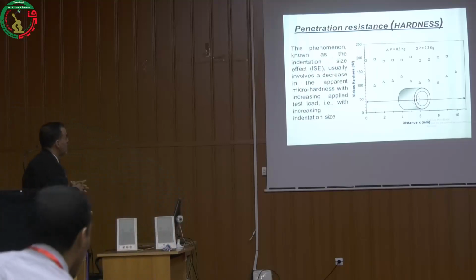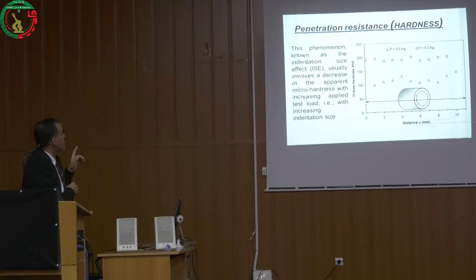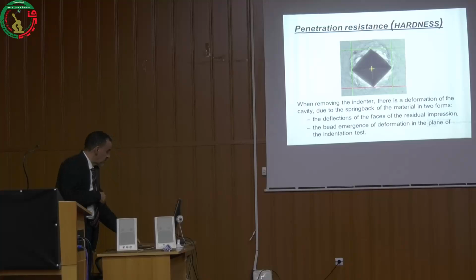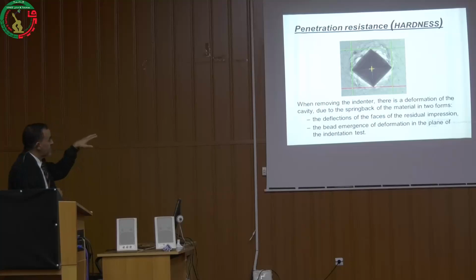This phenomenon is known as indentation size effect, ISE, which usually involves a decrease in the apparent microhardness with increasing applied test load. Here is a photo taken for the hardness test.